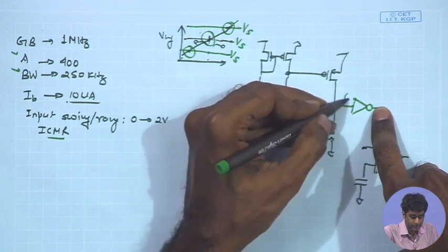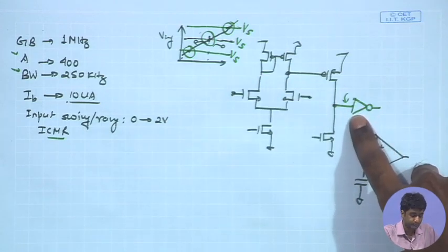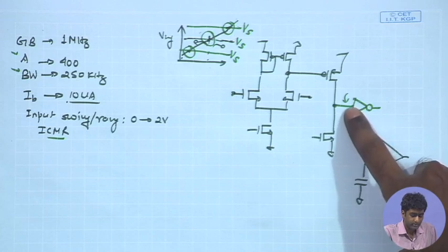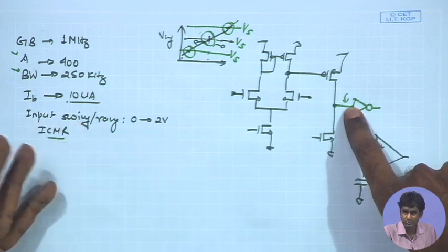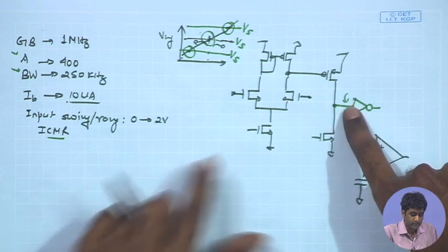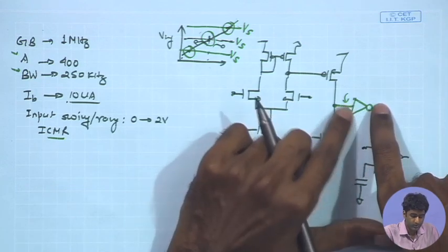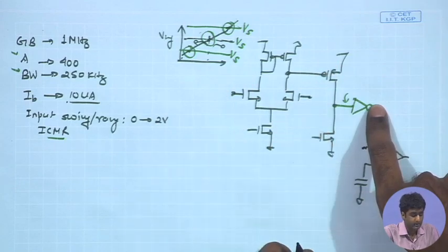So, in general, for a digital inverter, the parasitic capacitance at the input node may be once again of the order of few femtofarads to at the max few tens of femtofarads, and therefore, the overall parasitic capacitance over here may still be dominated by the transistors of the amplifier itself.